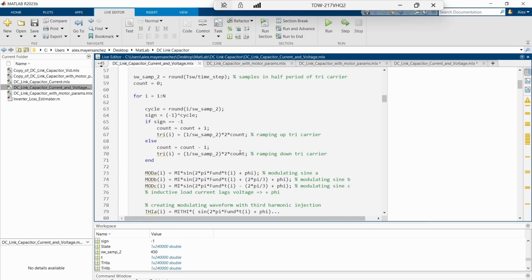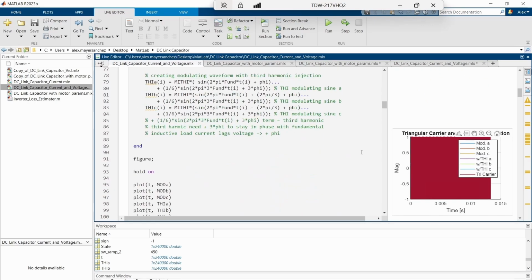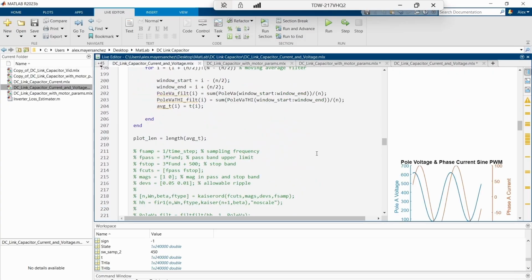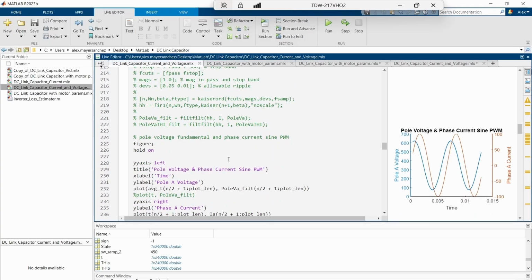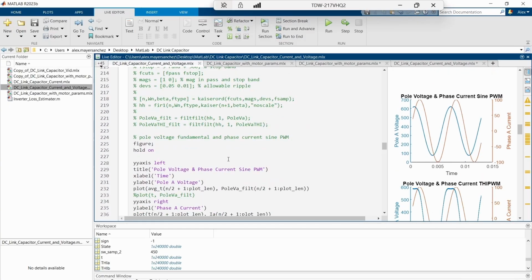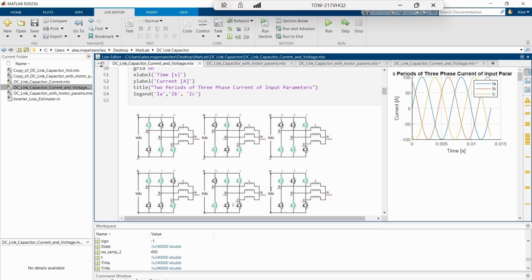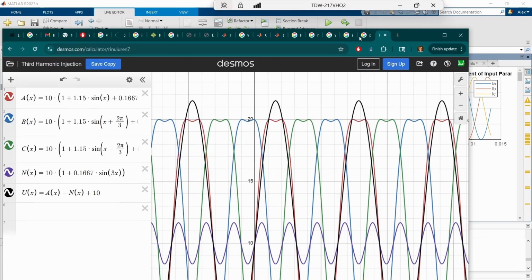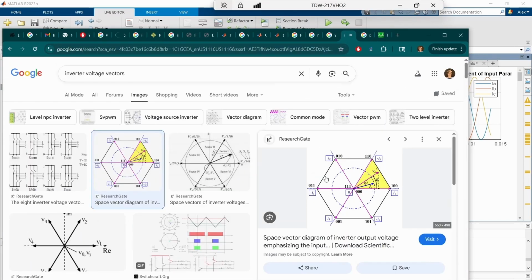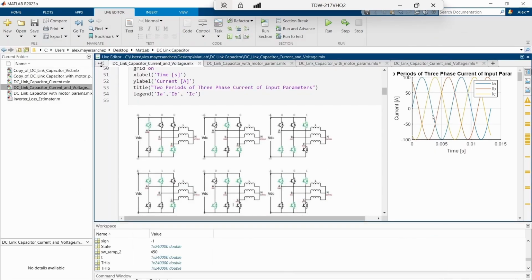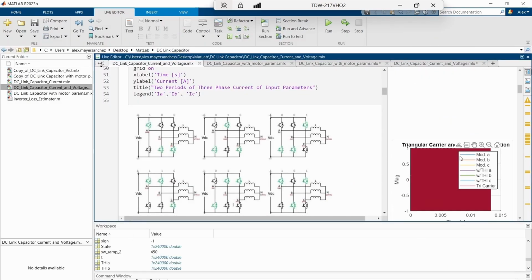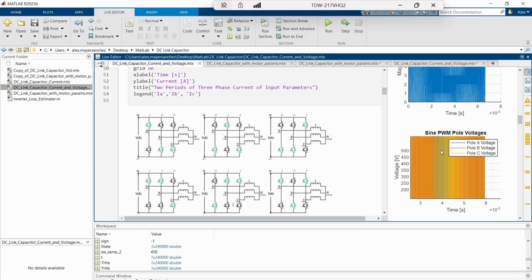So we left off with showing that changing the power factor shifts the phase and the voltage apart, and by turning off different switches we can put voltages in different sectors like this in order to create a sinusoidal fundamental voltage that we use to drive our load.